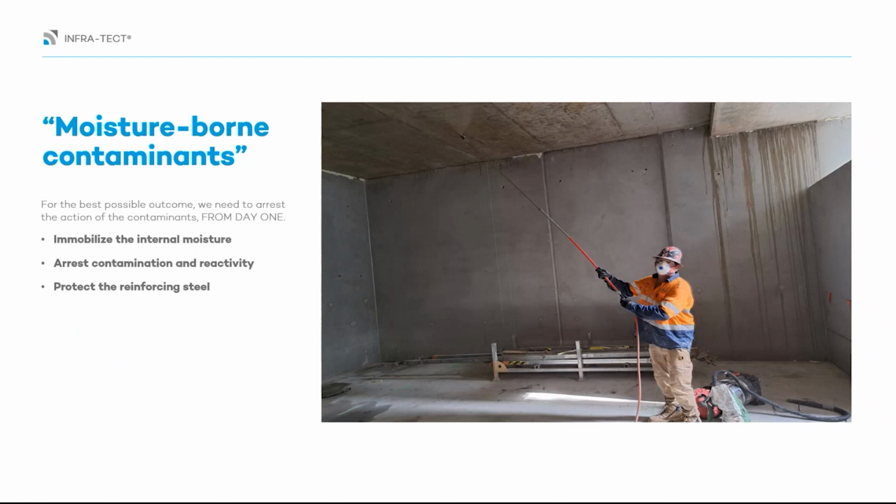And then that way, if we can encapsulate that moisture where it is and it can't travel through the concrete, then you're going to protect that reinforcement steel. That's the main one. It's the old saying, really, isn't it? Prevention's better than a cure. Yeah, absolutely. Preventative maintenance is going to save a lot of time and money on curing that structure in the future.